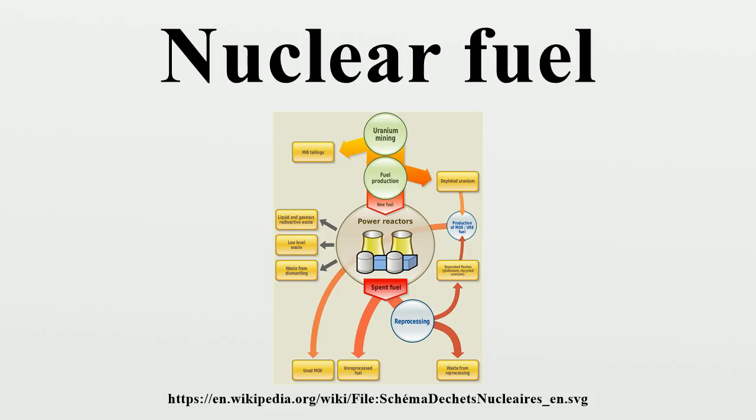There are about 179 to 264 fuel rods per fuel bundle and about 121 to 193 fuel bundles are loaded into a reactor core. Generally, the fuel bundles consist of fuel rods bundled 14×14 to 17×17. PWR fuel bundles are about 4 meters long. In PWR fuel bundles, control rods are inserted through the top directly into the fuel bundle. The fuel bundles usually are enriched several percent in 235U.